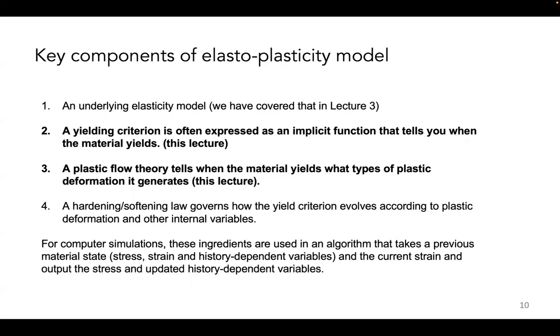And once the material yields, the strain is decoupled into the elastic part and the plastic part, and how the plastic part grows affects the stress you get. In the small strain theory, the stress equals C double dot the elastic strain only, assuming linear elasticity.